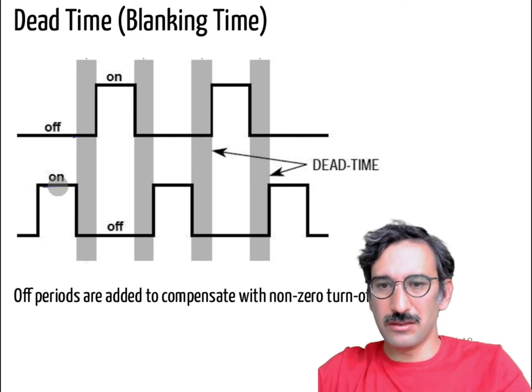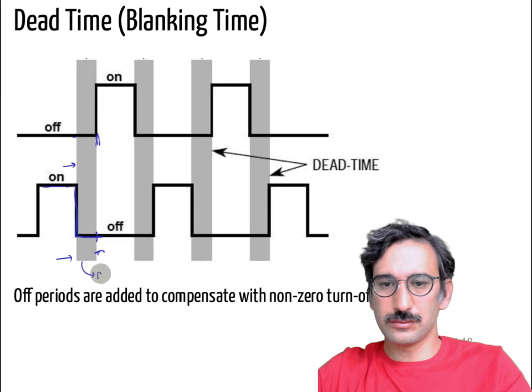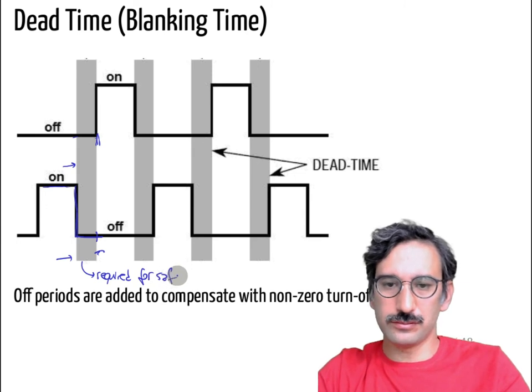So when one of the switches is turned off, you leave some time until you turn on the next one. Okay, that is required for safe turn off.